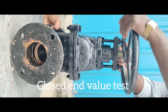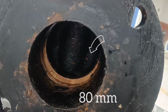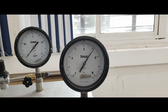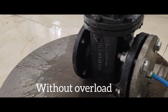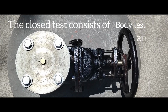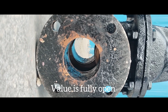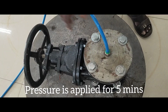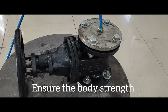Closed-end valve test. In this test, the valve is positioned vertically. For 80 mm bore diameter, the testing machine applies pressure of 10.2 kg per centimeter square without overloading the valve body. The close-end test consists of body test and seat test. In body test, the valve is fully open and the pressure is applied for at least 5 minutes after releasing air. This test ensures the body's strength.